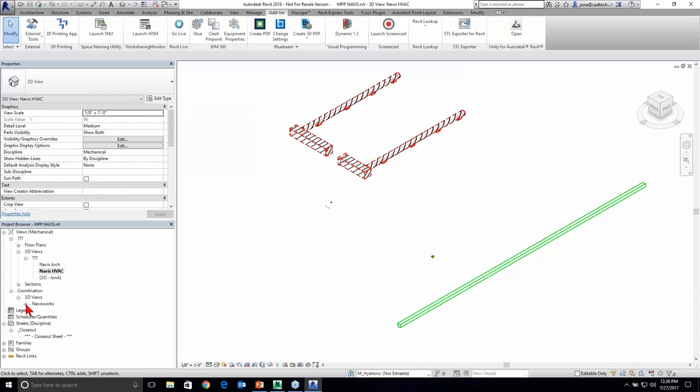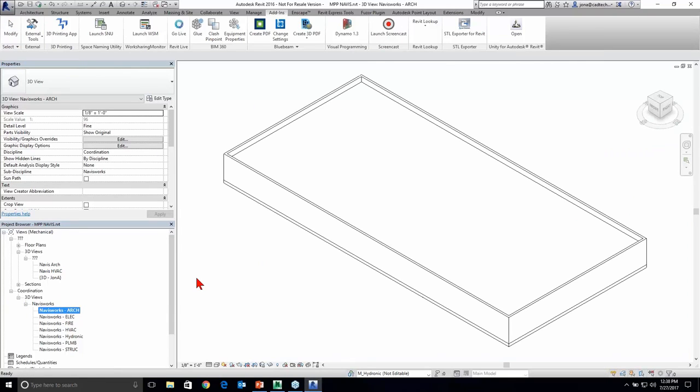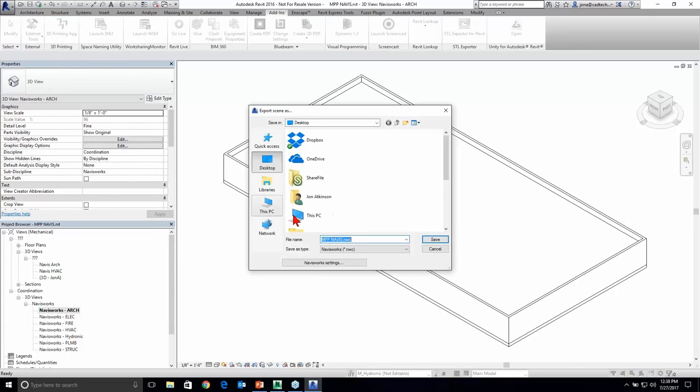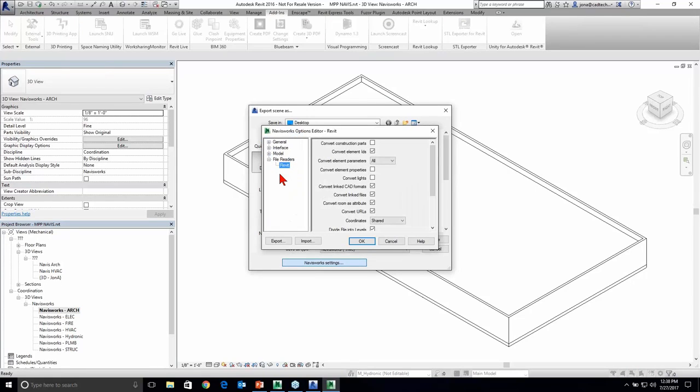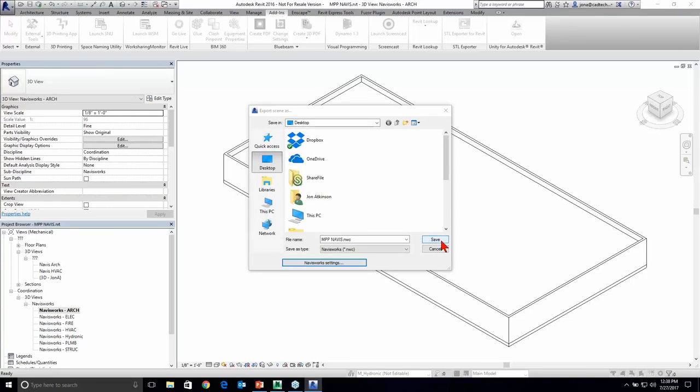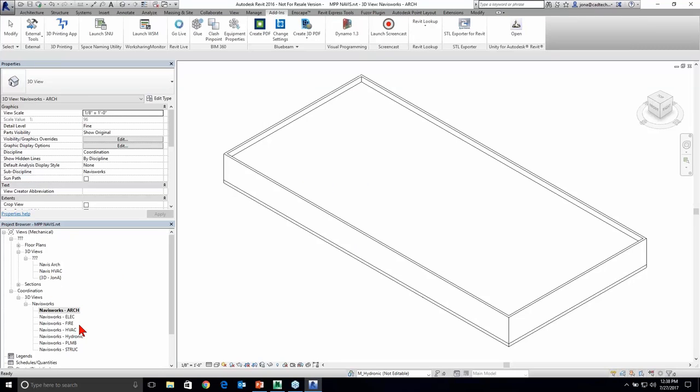Same thing with our Revit. I'd have some pre-made views in my template and simply go in, export, make sure that was my export linked was checked, so I don't have to open up all the individual models. I can do it right from the model I'm working in. Convert linked files, save, and go. And this would altogether probably take me 5 to 10 minutes tops to be able to go through. Once everything is preset, should be good to go.